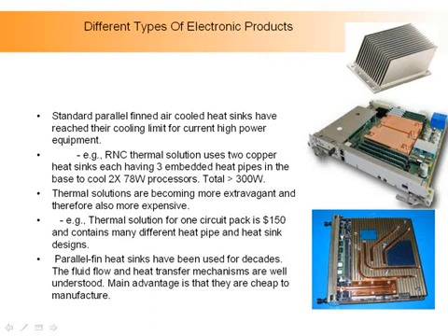And what you're seeing here is a heat pipe. Here are the hot devices. There's a heat pipe carrying the heat all the way down into the base of the heat sink and dissipating it out. So these are all various designs that we encounter, and these are all part of our products today. So again, as I pointed out to you, you've got to be able to work on these different areas of heat transfer or thermal design when you're designing electronic products.